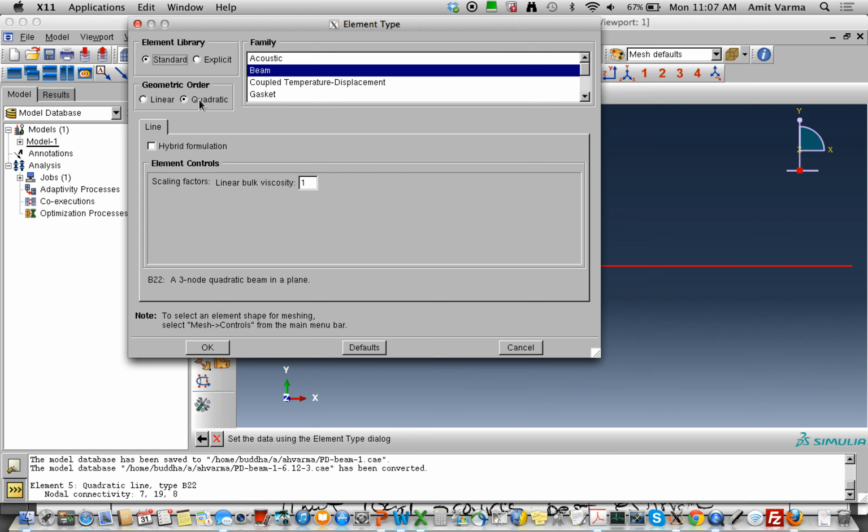If the Hermitian polynomial is telling you it's a cubic and you use a shape function that's cubic, you will need one finite element in order to solve the problem, because your shape function is exact. Whereas if you used a linear, you're probably going to need a lot more. Or if you used a quadratic, you would need a little more, few more finite elements. In this case, I don't need to worry about it because firstly, it's a nonlinear inelastic problem. I'm going to get all kinds of plasticity occurring, so the Hermitian polynomial is not going to represent. Later on, you're going to apply axial forces, and the Hermitian polynomial does not work for that.